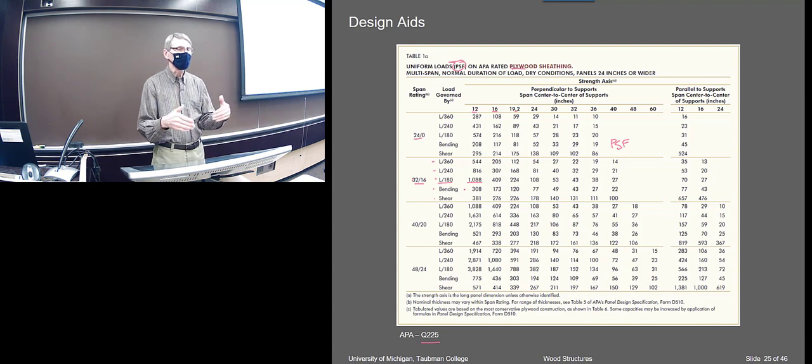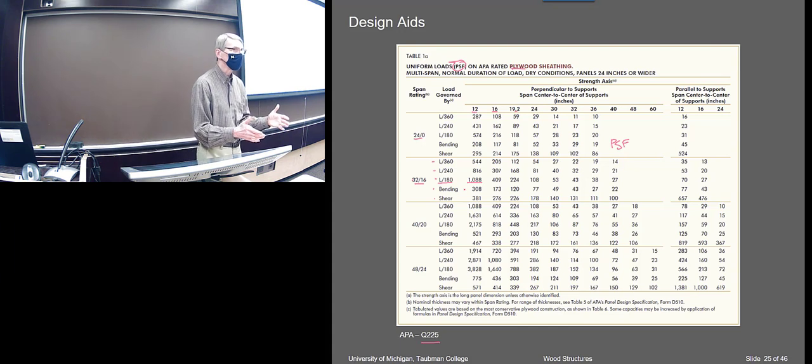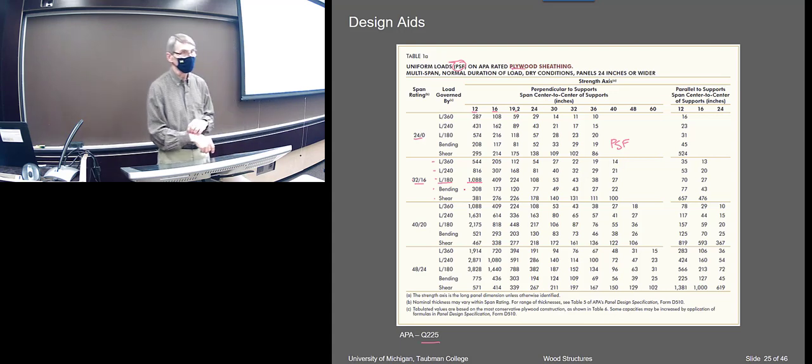And the load on it, although your floor loading may only be 50 psf, you weigh more than 50 psf, right? And in that small confine, you will definitely get a 200-pound per square foot load. I think that's even the code load, point loads come out to about 200, as I recall.